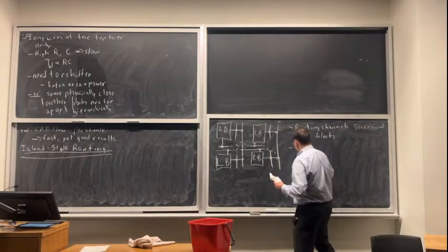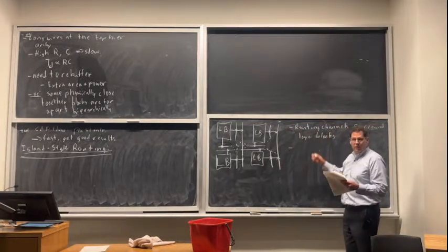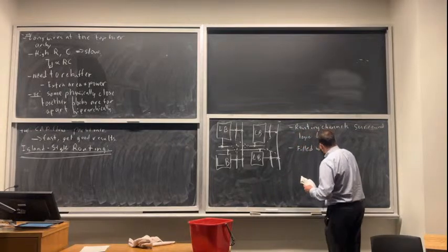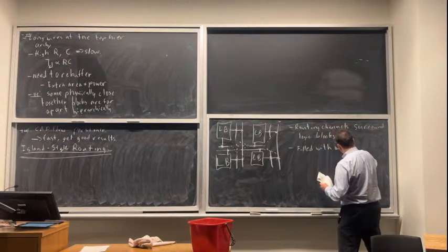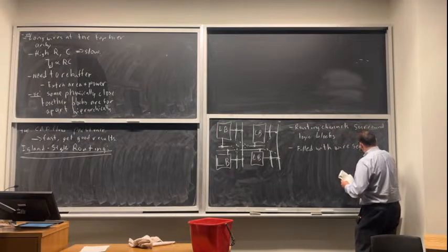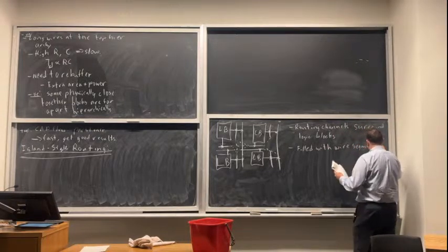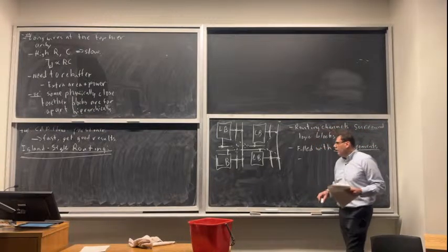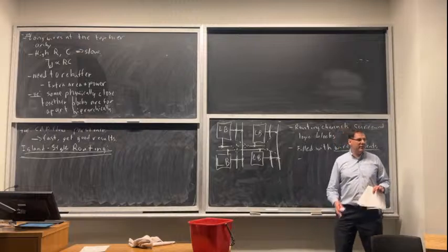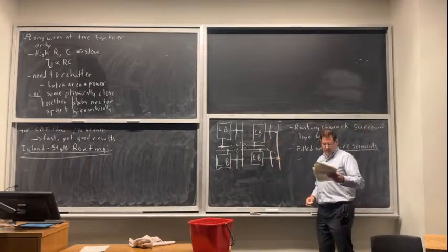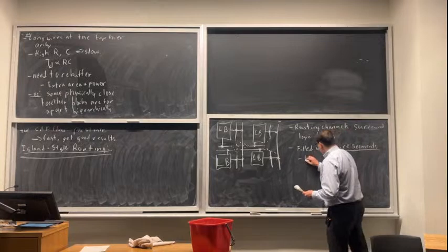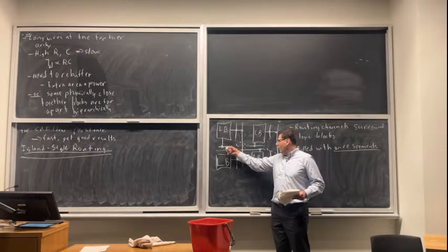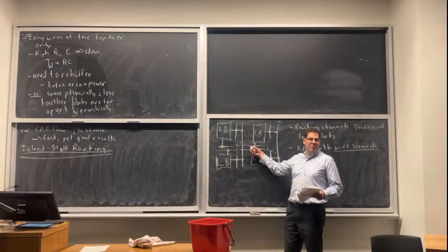Okay, let's define a little terminology. Those routing channels are filled with wire segments. A wire segment is a piece of wiring that goes past a certain number of blocks. Usually we make different lengths of wire. So this would be called a length 1 wire. It only goes past 1 block, and you have to go through a programmable switch to keep going.